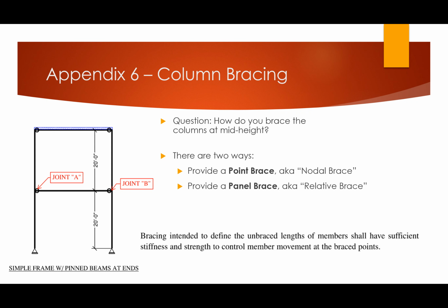Okay, and I should point out, point brace and panel brace, that is new terminology given in the 2016 version of the Steel Code, AISC 360. So if you have the Red Book or anything before the Red Book, it's not going to use this terminology.